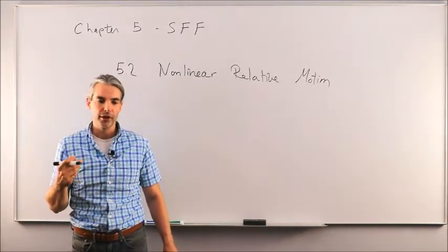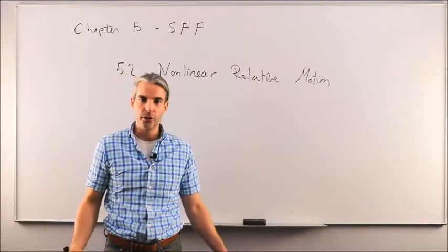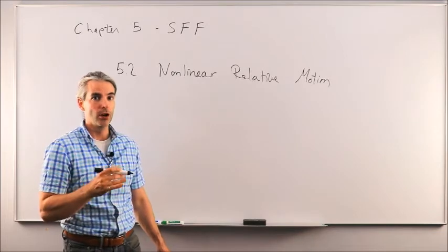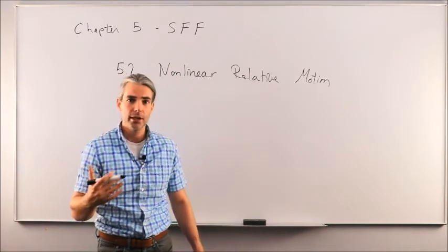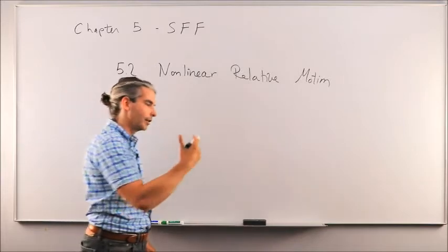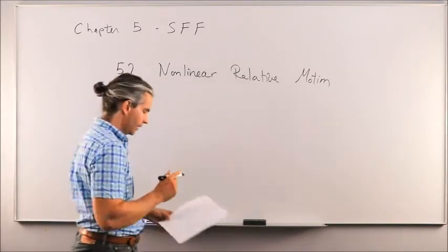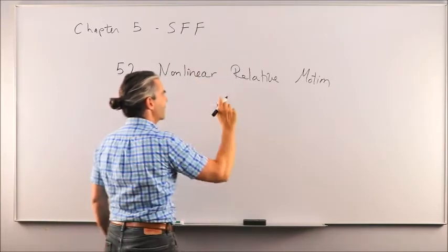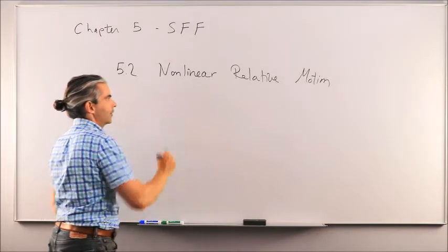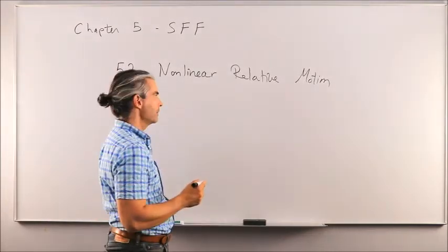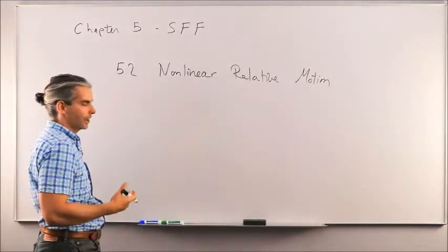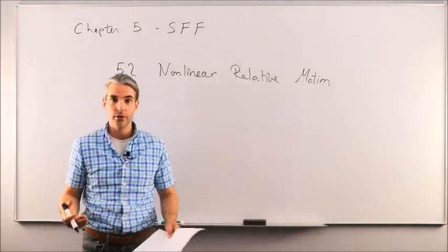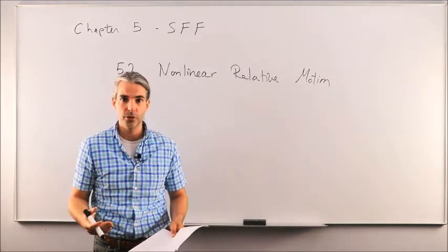So we're not concerned here about rederiving the two-body equation of motion, which would be the spacecraft motion with respect to the planet. That's no longer of interest here. What we really want is to obtain the motion of one spacecraft with respect to another one, okay? So this is referred to as relative motion. And the first thing we'll do is to derive the exact nonlinear equations of motion for that scenario. And then we will look at simplifying assumptions to then obtain a linear model that will be used to predict the relative motion on orbit between two